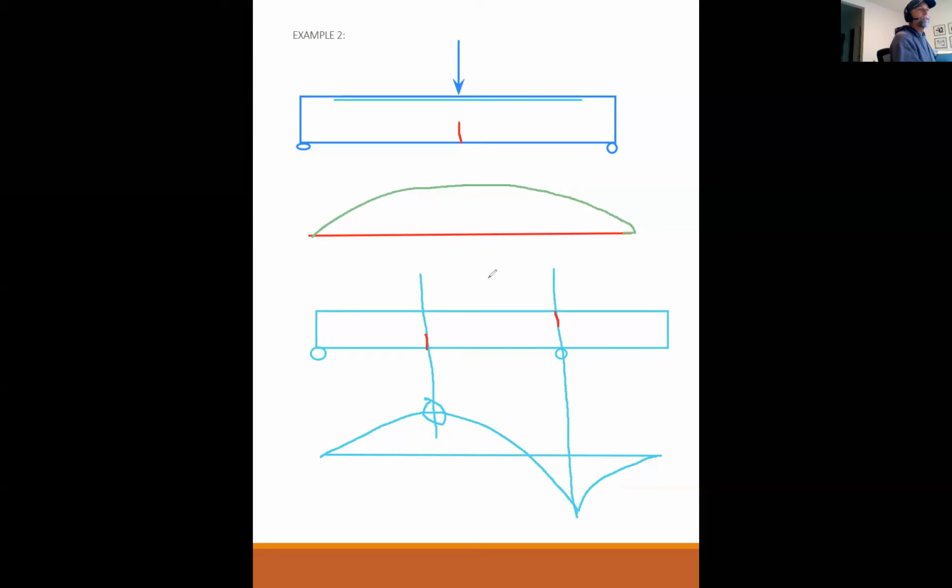The bottom or the top are in tension only due to the moment diagram. That is the only thing that tells you if you have tension in the top or in the bottom. Okay, so that answers where is it going to crack. Where it's going to crack has nothing to do with where the steel is. But where you put the steel better have something to do with where the crack is. But the crack doesn't locate the steel. The steel must be located to find the crack. All right, so the moment diagram dictates where the tension is.